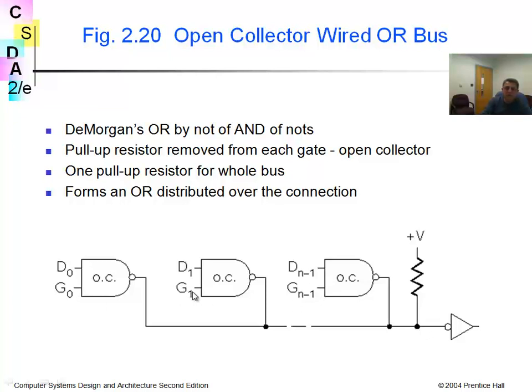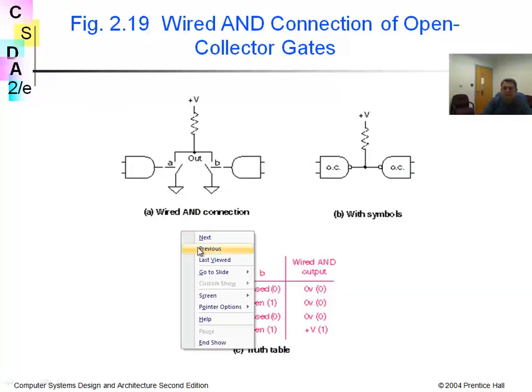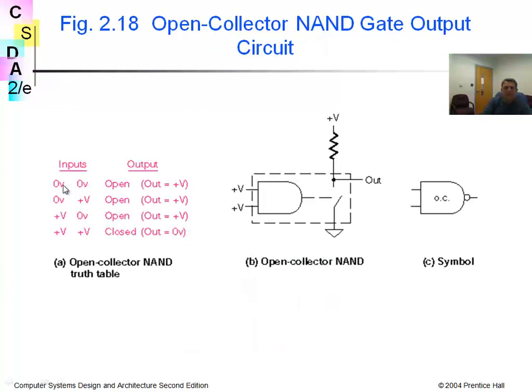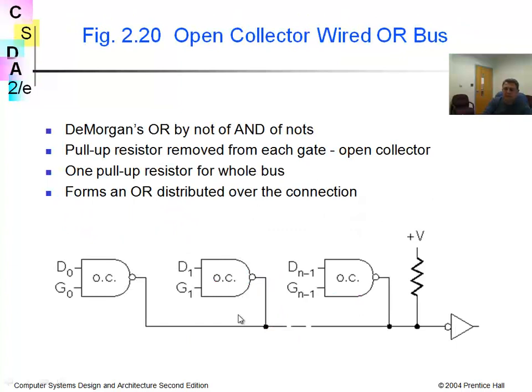If the inputs are 0 and 0, based on the NAND gate we looked at earlier, you will get a 1. 0, 1, you get a 1. 1 and 0, you get a 1. This is an inverted AND gate output. Then 1 and 1, you get a 0. So this is exactly what happens. Then you can gate one at a time and get all of the information correctly.